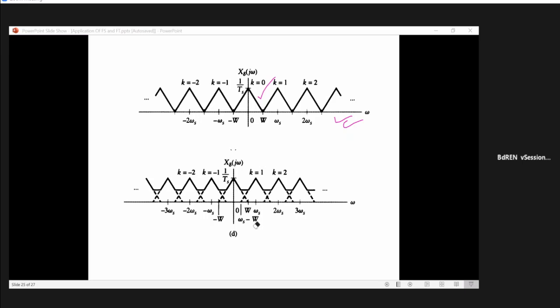The reason is that if you increase the sampling frequency indefinitely, that is, you are oversampling, what will happen? It will overburden your system, isn't it? Because if more samples are there that are not required, the bandwidth requirement for your processing will be higher, and you will have many redundant samples. So this is not the way. You have to set an optimum frequency so that your system will operate without overburdening its components.